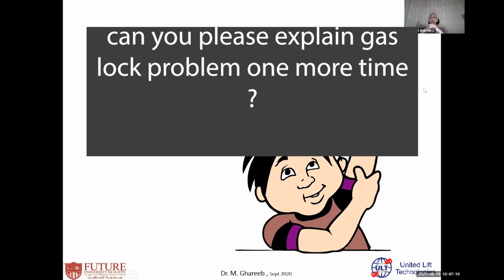Yes, gas lock. It means you have gas inside your pump. For my pump to work and run smoothly, in the upstroke, my traveling valve should be closed and the standing valve should be open, allowing fluids to enter the pump.